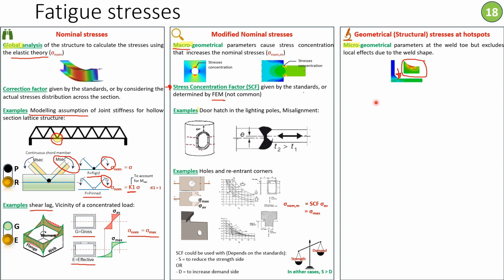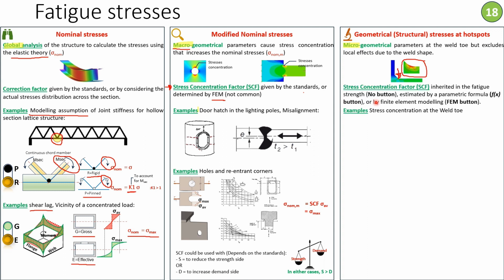Now for the geometrical stresses at hotspots, again, you still need to capture the stress concentration at weld toes, or hotspots as they are called in the codes and standards. You still need to calculate the stress concentration factors. There are several methods to do that, but before delving into this, we need to clarify something first.